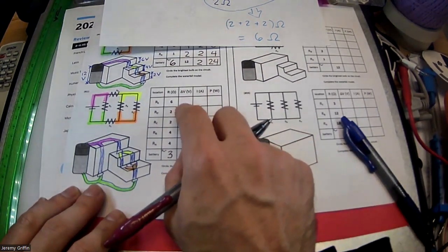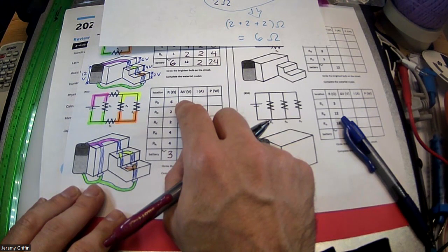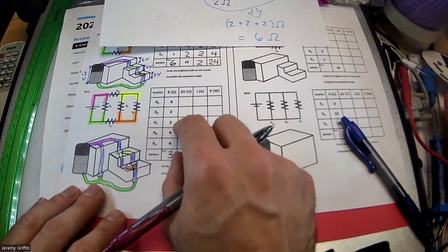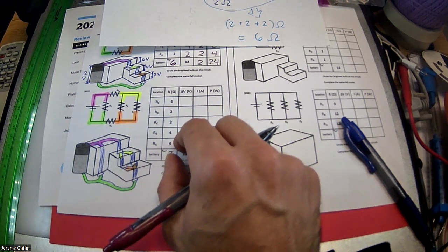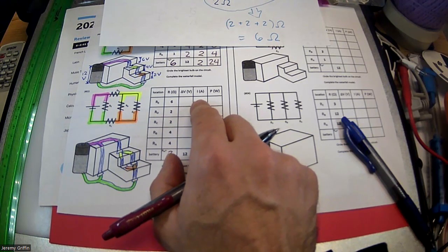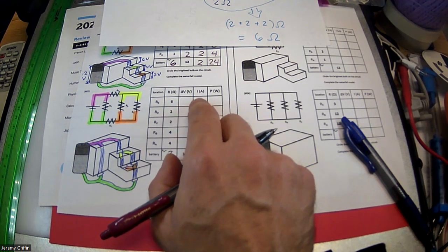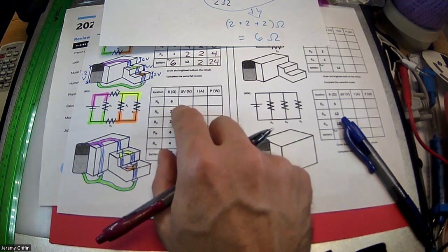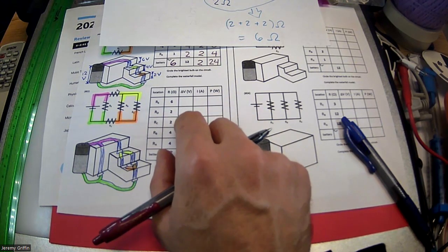Okay. Next column, what's the voltage drop at each resistor? Now this is probably the most difficult column to figure out, but now that we've gone through one of these tables, you kind of see where this is going, right? Once we figure out all the voltage drops, the current we'll just use Ohm's law, I = V/R, chug, chug, chug. And power is just going to be I × V, chug, chug, chug, right? So we're at the hardest step right now. What's the voltage drop?